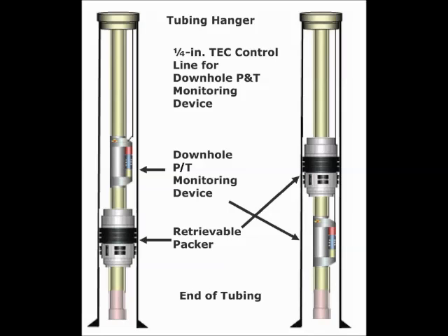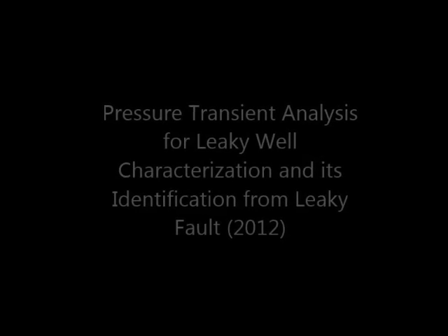To solve it, we have to address the gauge placement issue by keeping the points below while installing a downhole pressure sensor. The pressure gauge is placed as close as possible to the perforations. For sensors without sand control, a mandrel with pressure gauges near the perforated zone can be placed. For stacked completions without sand control, the gauges can be run in the producing zone.